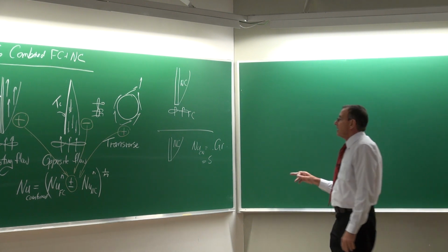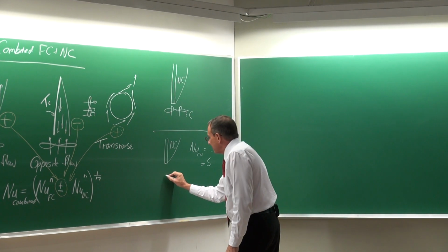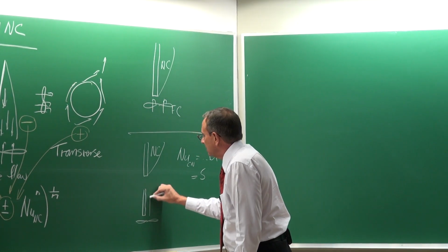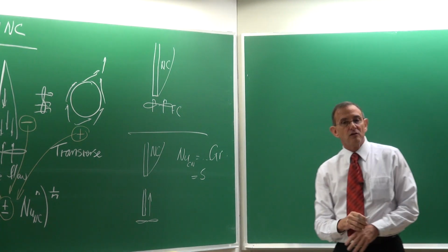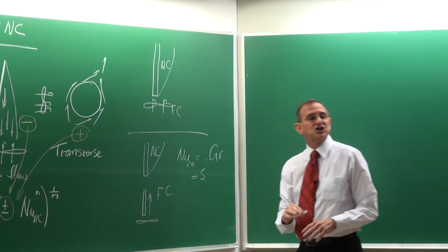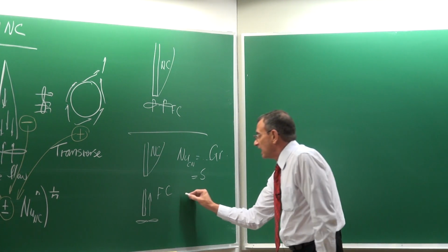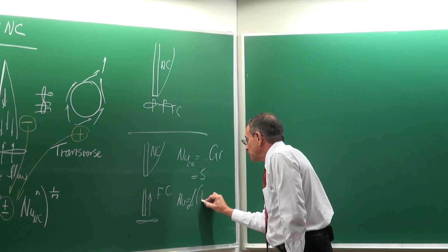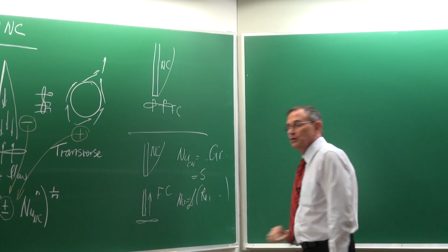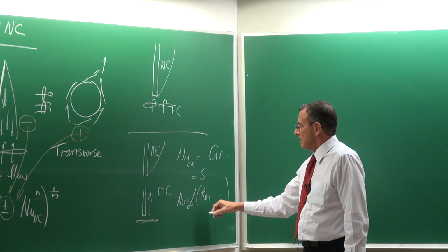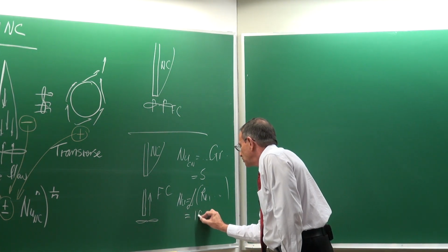Okay? And then you would ignore that part and you would say, well, this is a flat plate and I've got a fan and the flow is over the plate. So I would consider this as forced convection only. And I will go and calculate the Nusselt number. It will be a function of Reynolds number. You've done it already in chapter 5 or something like that. Okay. Now let's suppose this value is equal to 10.